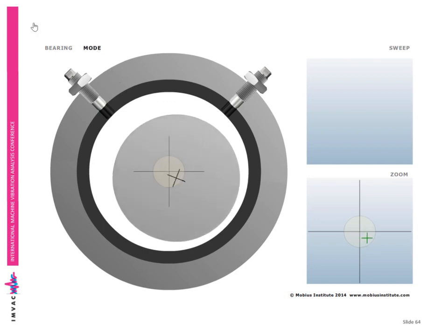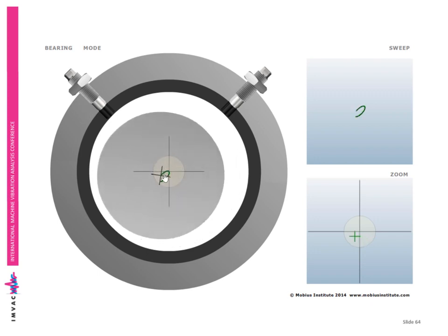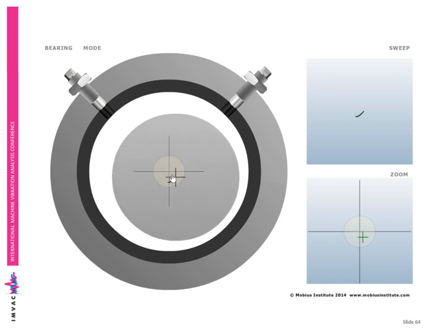And when it's rotating and moving in a sort of orbital motion like that, or elliptical motion there, we are very interested in whether it's doing it here or over here or up there. That tells us something about the stability. The shape of the orbit tells us about the fault condition.